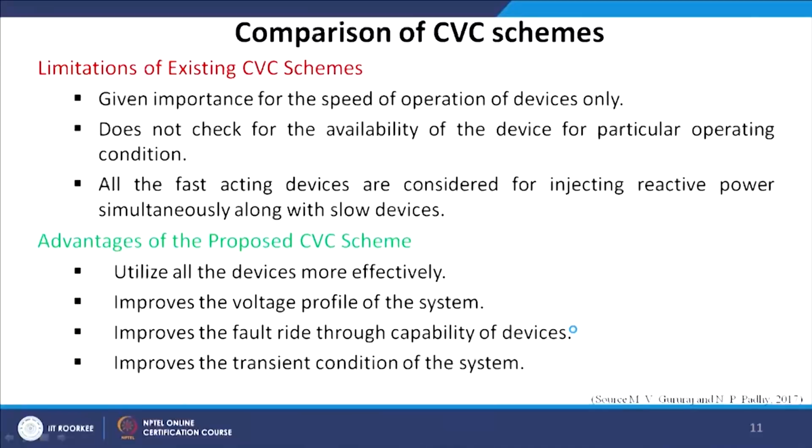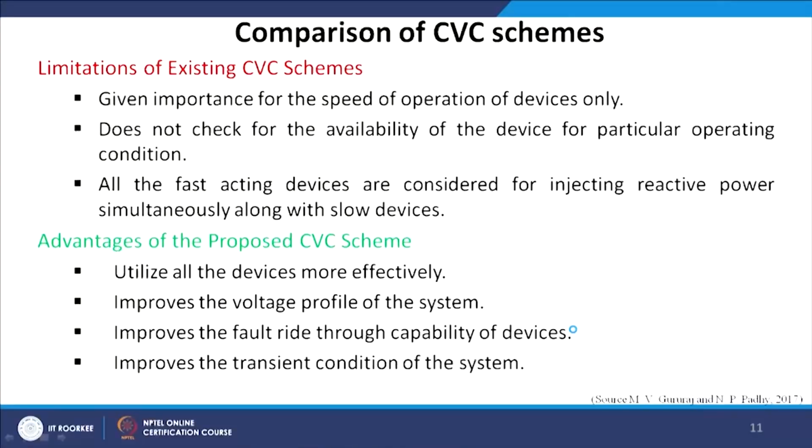In the proposed model, what we have suggested is to utilize the devices more effectively. Even the OLTC, STATCOM, DFIG, DC microgrid, all of them have to participate simultaneously, by which it improves the voltage profile of the system at large, it improves the fault ride-through capability of the devices, and it also improves the transient conditions of the system.